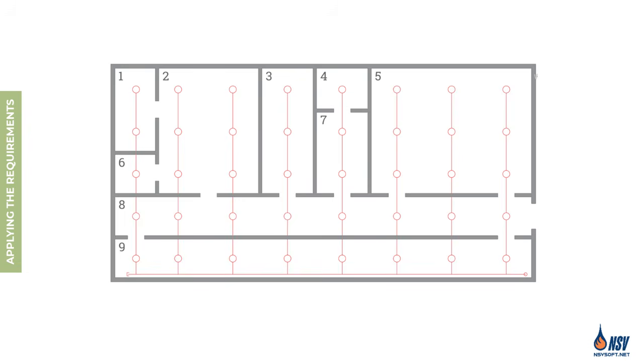Now let's apply the room design method to determine how many sprinklers should be assumed to operate in the hydraulic calculations. In this example, the rooms are classified as light hazard. The lintel height is 10 inches and all openings are 3.5 feet wide. The doors at these openings are not automatic or self-closing. We start with room 1.